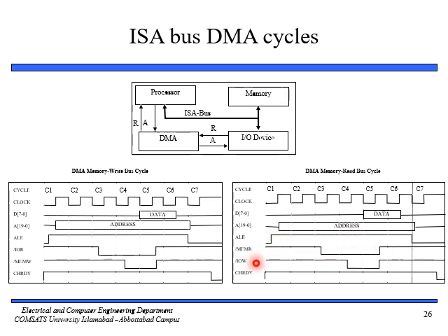This is going to work because this is slash memory read. It means that it's going to work on logic 0. So during the third and fourth clock cycle we are going to read. So this is initiated, and in the fifth clock cycle we are basically reading the data.